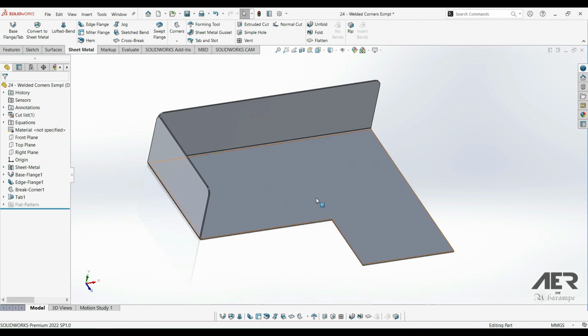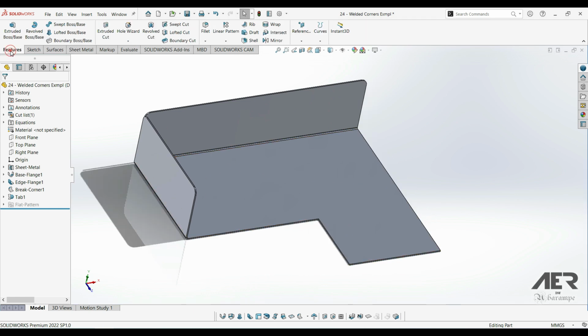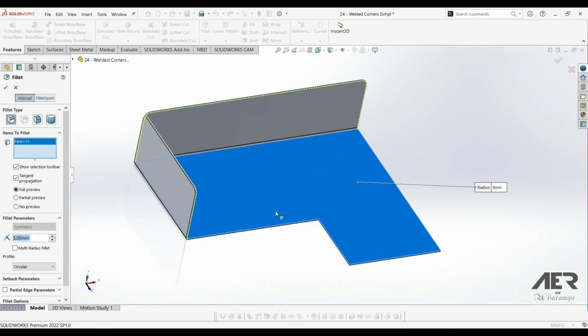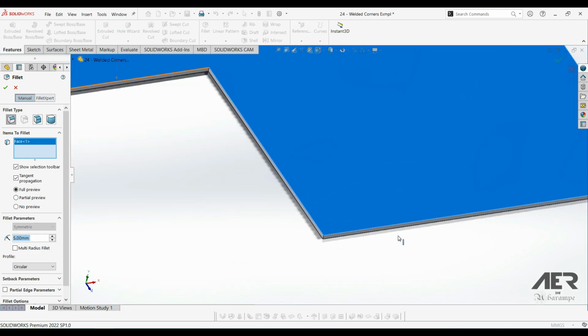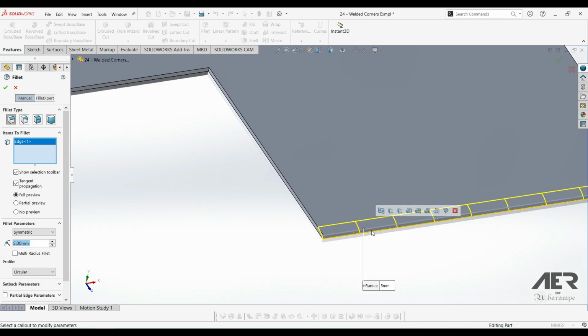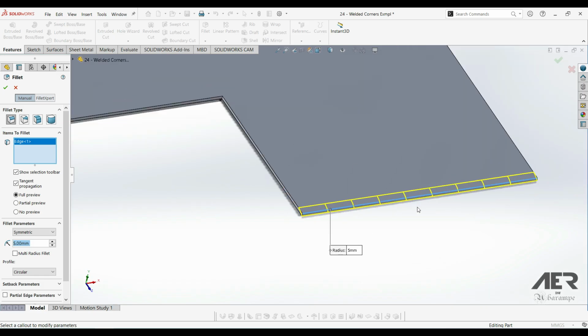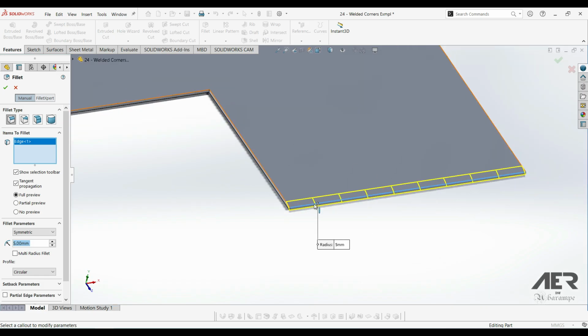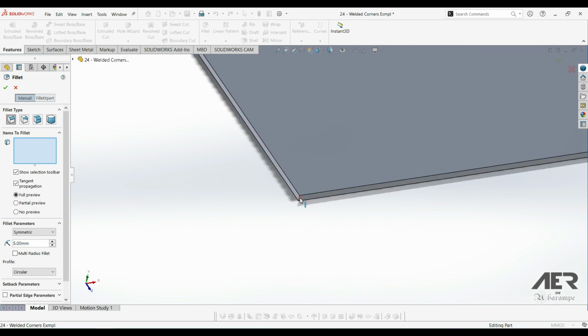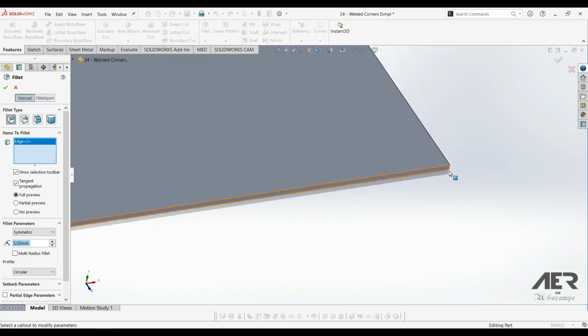If we try to do this with the fillet tool, so we select the fillet tool, set the same size, and then try to select that face, it just won't work, so we could zoom in and select those edges individually. It's quite easy to select the wrong one. If you select something like this, then it's really hard to make something like this in sheet metal, and we don't actually want this. We just want these small vertical edges. So we can just zoom right in and choose them manually. Just a very simple model, so it's quite easy to do.